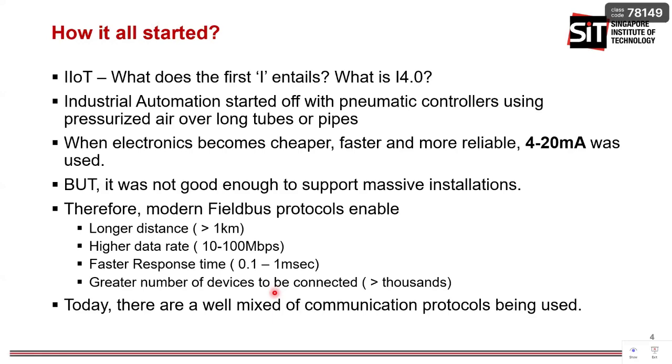However, the number of devices that we are connecting is really huge. All right, we are talking about having more than thousands of devices connected. You can imagine a campus, with many of you connecting to the Wi-Fi network, right? But in a factory, to have devices, machineries, equipment connected, we are also looking at the number in the range of thousands. And there are many different communication protocols being used today, and this may spell some problem also. So in today's lecture, other than talking about what fieldbus is, I would also like to share with you the constraint with regards to having too many different protocols altogether.